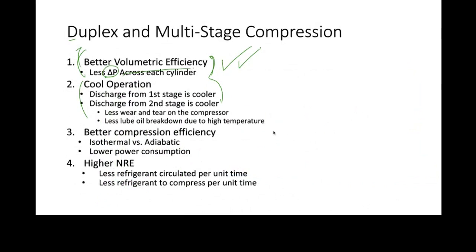It's easier on the oil. The lube oil is more effective. The lube oil doesn't break down due to high temperature. Less wear and tear on the machine. So cool compressor operation is a much better thing. And what it also means is that it increases our condenser capacity.